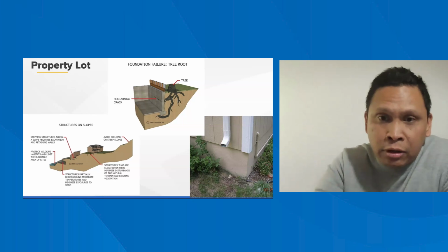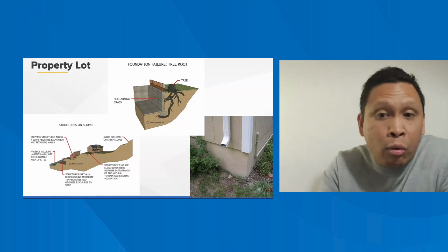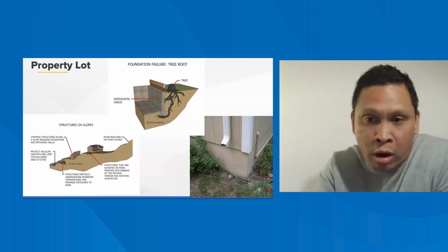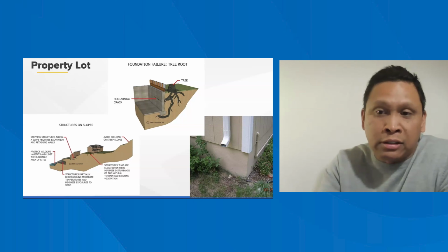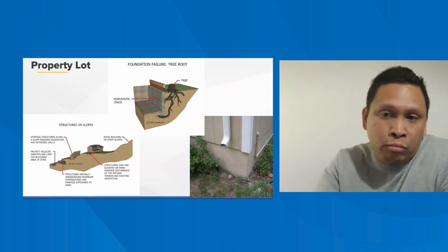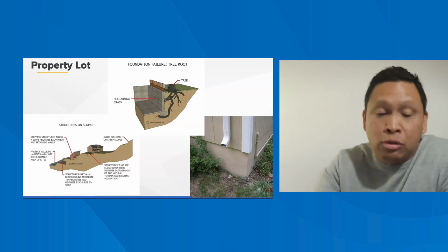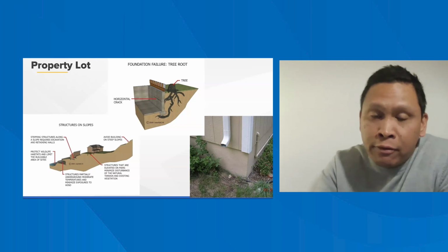Rotten sills, like the bottom sill, can be crushed by the weight of the home over time, especially if it's constantly in contact with water, which can lead to settlement of the home. And rotten sills weaken the anchoring of the framing system to the foundation wall itself.